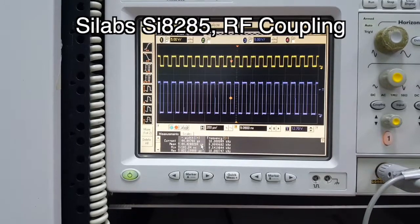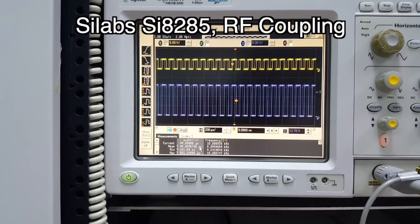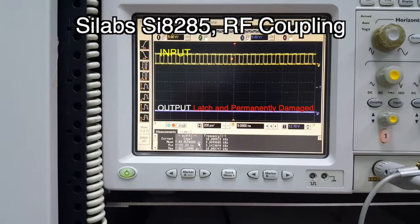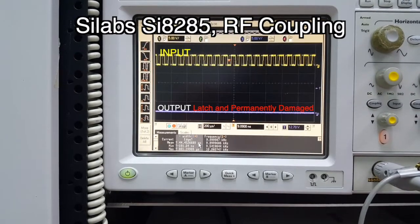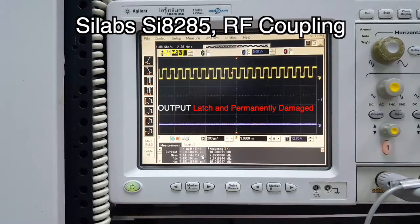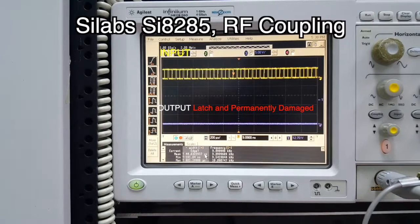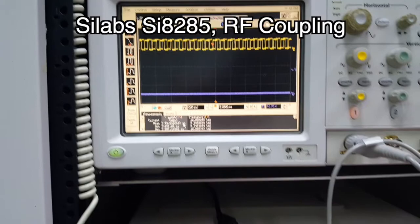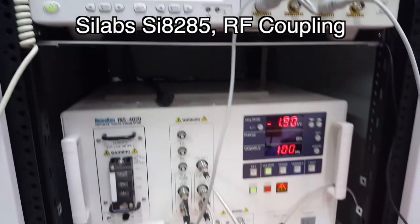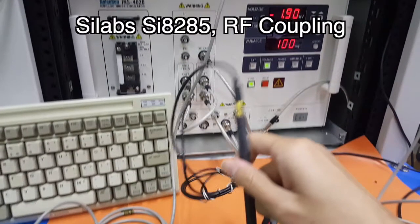The next gate driver we're going to test is Silicon Labs Si8285, which uses an RF transmitter and receiver to couple the signal over the semiconductor-based isolation barrier. It has a DSAT pin to detect the desaturation and shuts down the driver in a controlled manner. The SiLabs gate driver is good and does not have any missing output pulses. However, when impulse noise is increased to negative 1900 volts, the output latched. When latched, the driver is drawing excessive current and is permanently damaged.